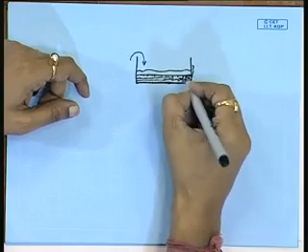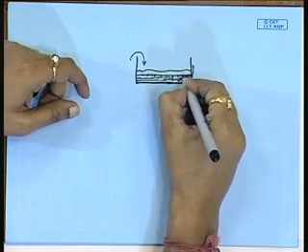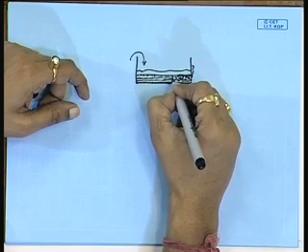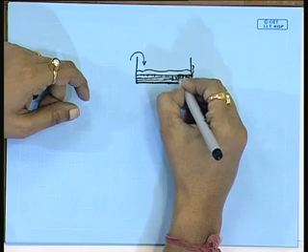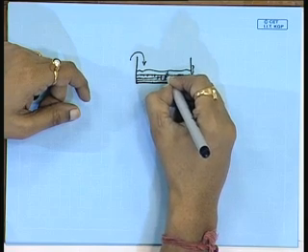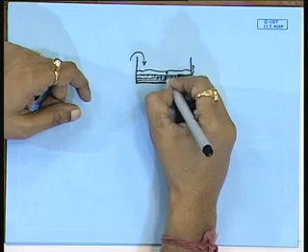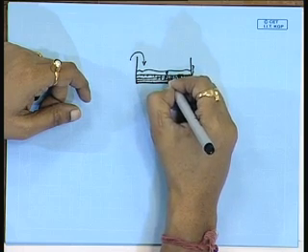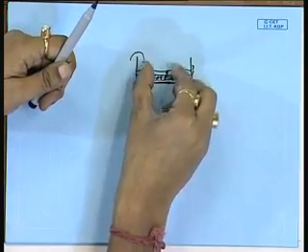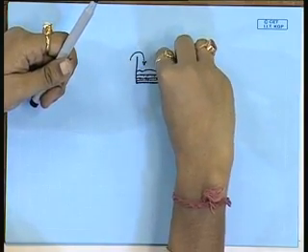Now, during fermentation, when heat generation is taking place within this bed volume, as the bottom side is continuously in touch with this liquid medium, heat is getting absorbed into this bottom liquid, and so the heat generation within the bed is taken care of.